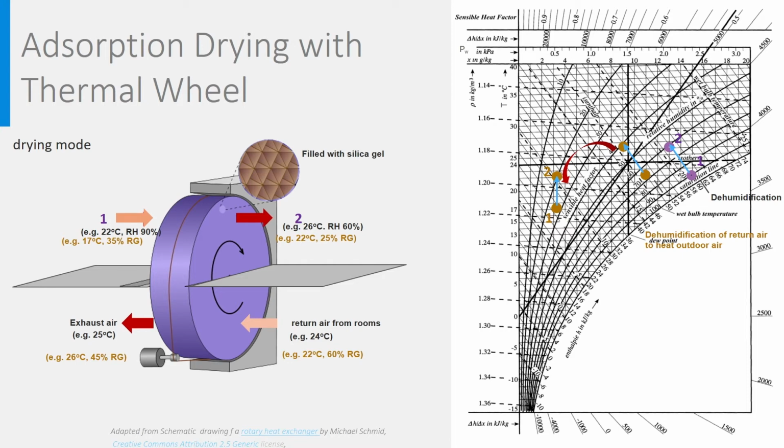This works as a cycle, and once the silica gel is saturated, it has to be regenerated by circulating air through it at high temperatures above 100 degrees, by which energy is used. This is called the desorption process and costs energy. That can be calculated by taking the latent heat of evaporation of water times the total mass of water that have been absorbed by the silica gel. Additionally, it may be that pollutants are also absorbed in the wheel and transported to the supply air.